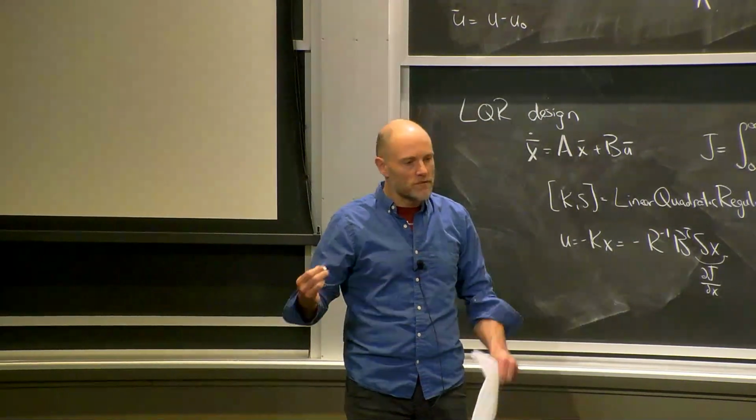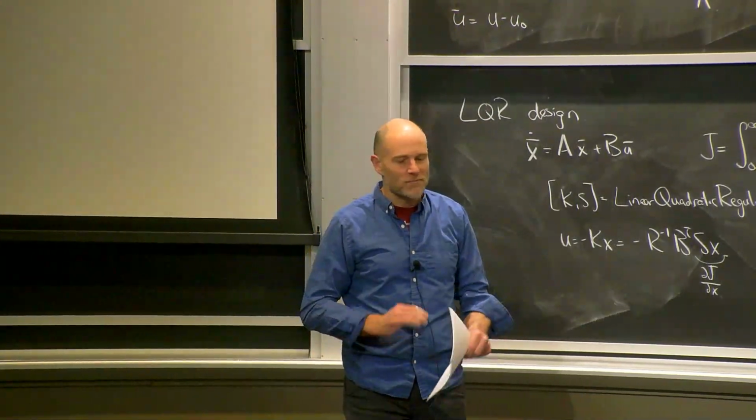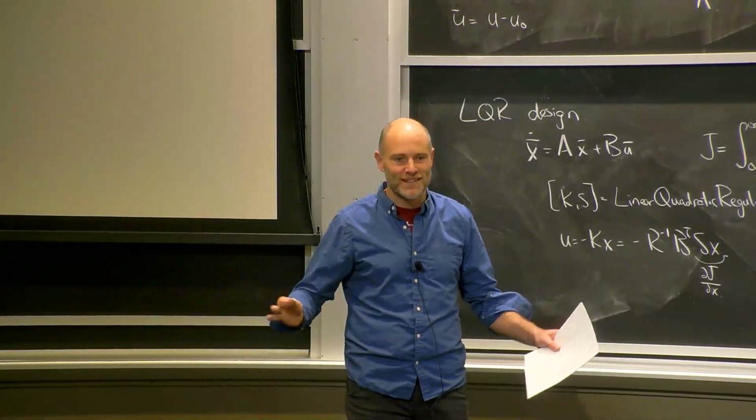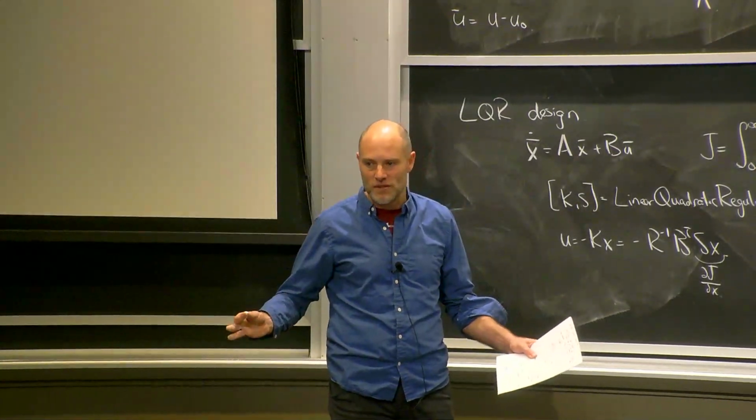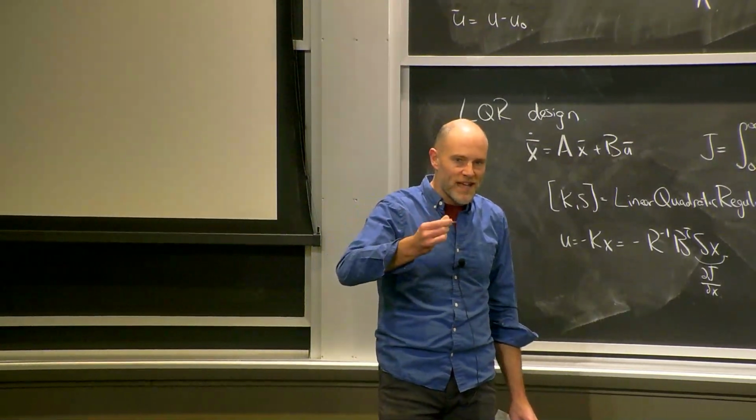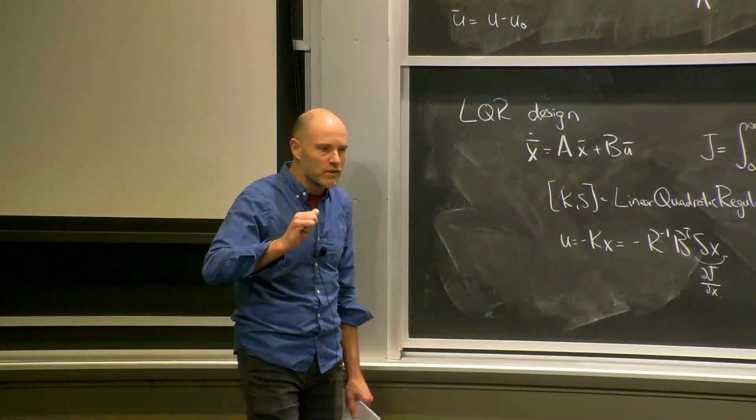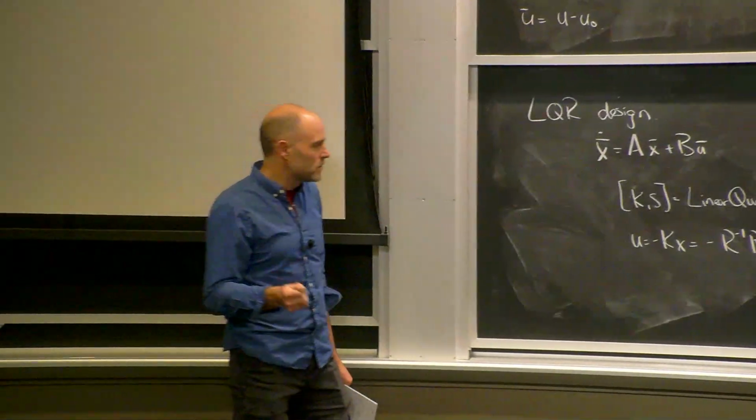Some people say, oh, you just shifted the problem, and now you have to pick Q and R. But that's way, way better. You can pick pretty much any Q and R, and it's going to give you something good. Dialing in your performance exactly, maybe you have to think a little bit more about what Q and R should be, but it's almost always good.